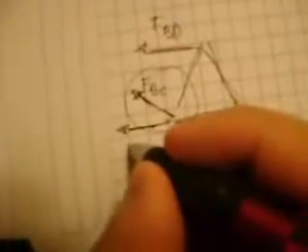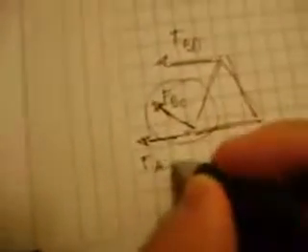Now, to get the force in BC, you use the method of cross sections. So you cut through the members, and then you get these loads. You put all of them in tension. You have force BD, your force BC, which is the one you're looking for, and your force AC, I think. Yeah. And then you have this load P and the force in the y direction that we already know. You also have your force in the x direction, but you really don't need that.